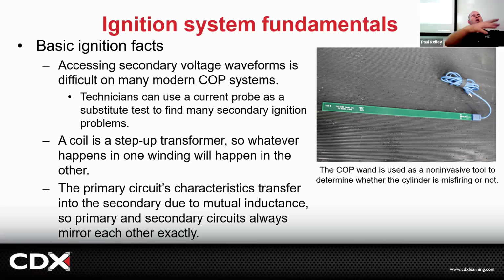The primary controls the secondary. And I'm looking at chewed wires in the picture of the primary. Forget about the spark plug. The spark plug's on the secondary. The spark plug probably is not sparking. I agree. But it's not sparking because it's not getting the correct voltage from the primary because the wire's chewed, dude. Duh. Okay, makes sense?